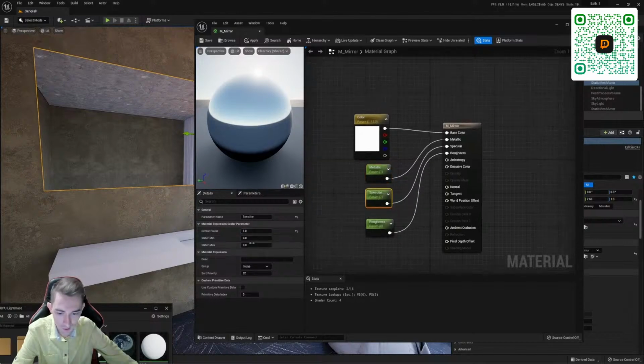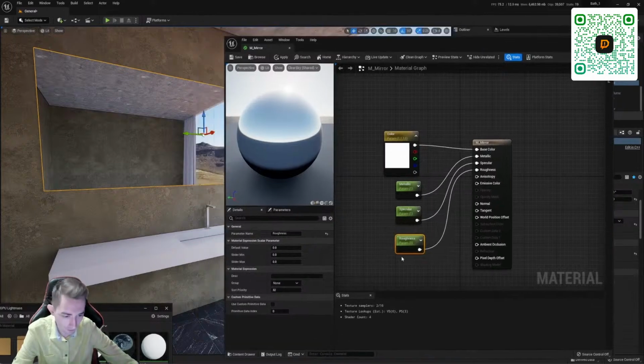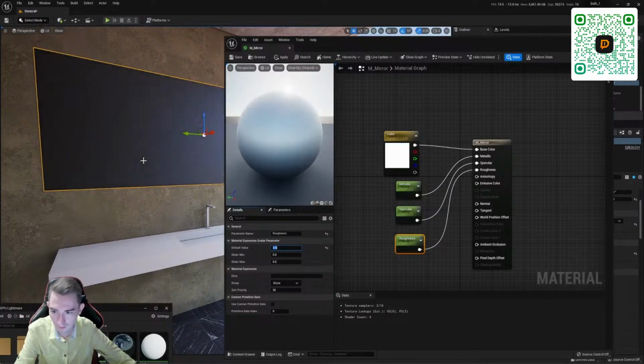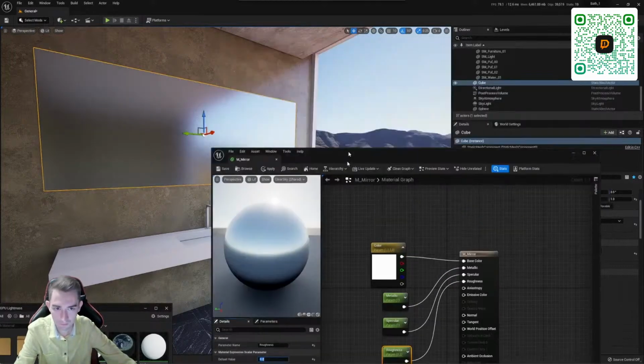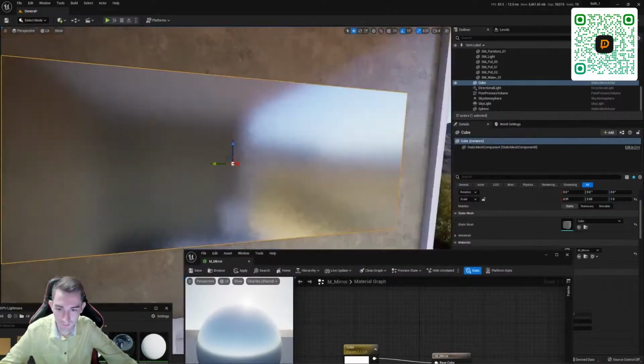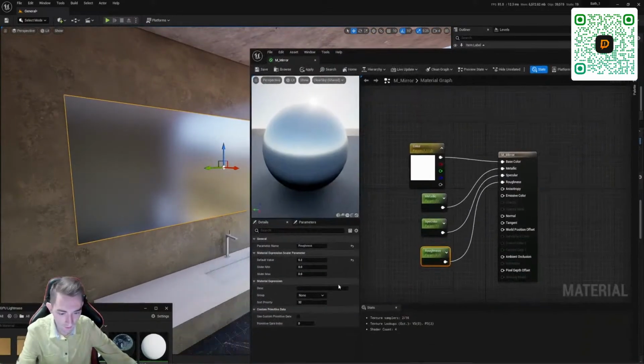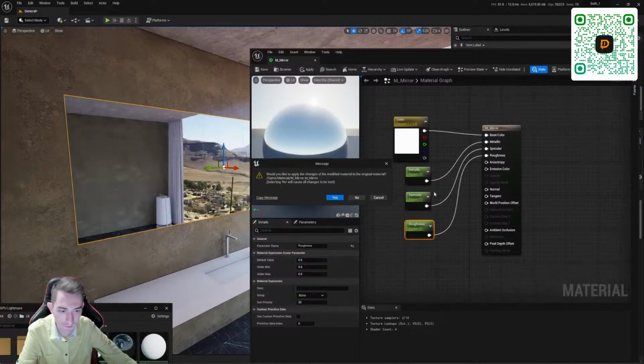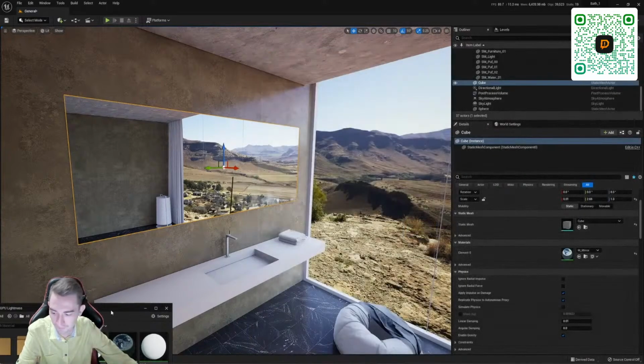This is our reflection. We will definitely put a reflection. In principle, you can leave it out, I'll look, but I will not leave it. Next. Roughness is our roughness: 0 is our completely glossy mirror, 1 is completely matte. So I'm changing the value here. It turns out that this is matte. It's more like metal here now. So we put 0. Great. We have sorted out the material of the mirror.